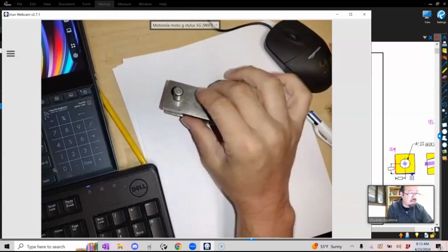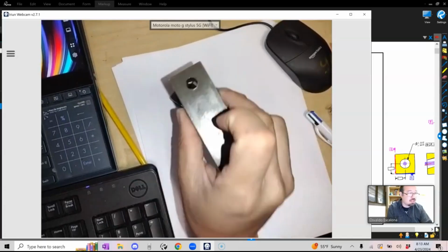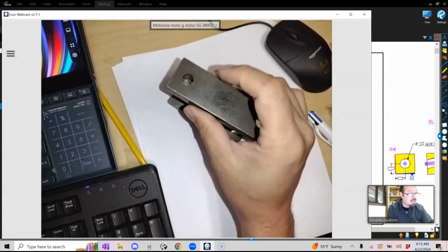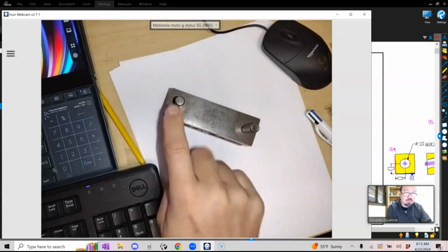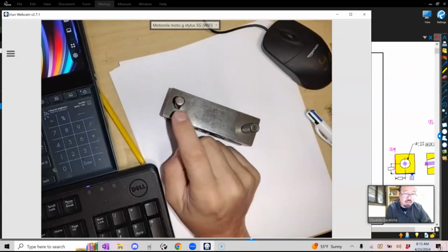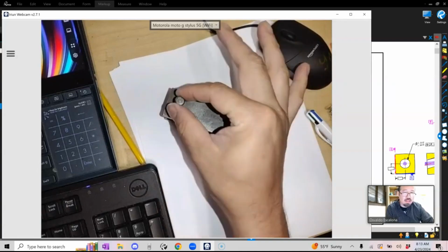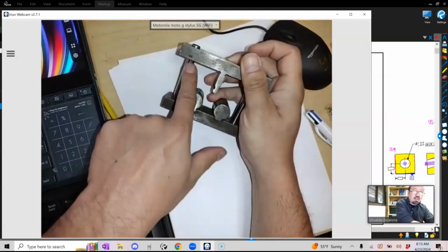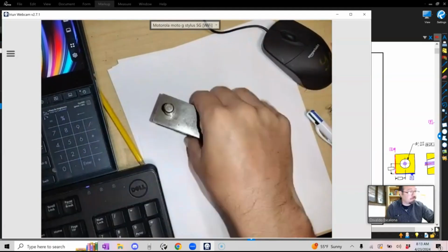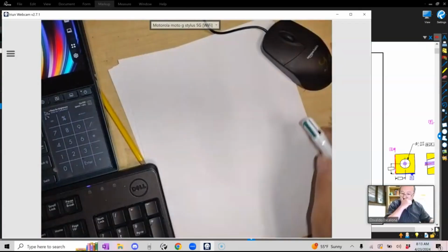Before, I only accounted for the size, plus and minus. Now, the problem is when I have things that need to mate with each other and they have geometric imperfection. It's a little bit crooked. It's not perfectly in line. Maybe it holds the size, but I know about the crookedness on this pin, either external or internal. So we gotta do something about it.